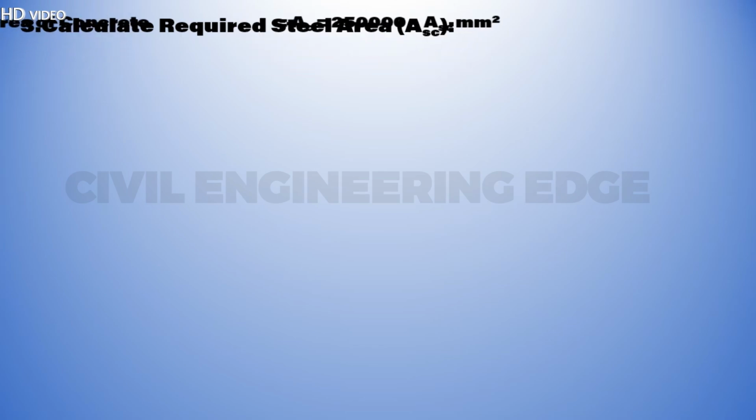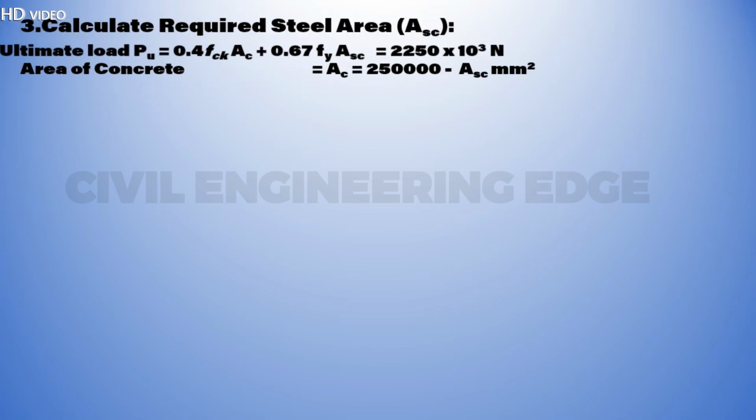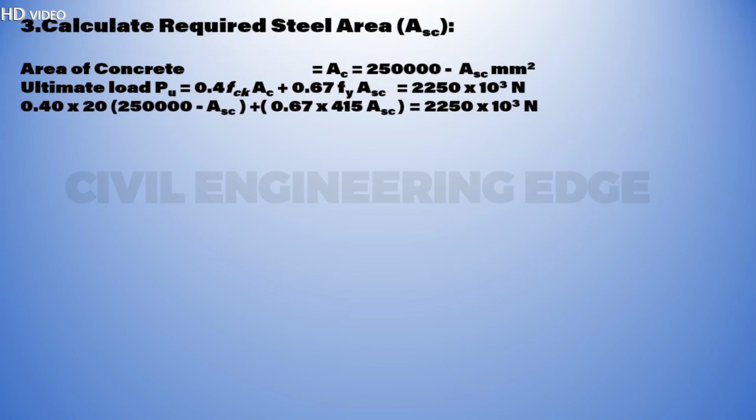For lateral ties design, the diameter of the lateral ties shall be not less than 1/4 diameter of the longitudinal bars equals 20 divided by 4 is equal to 5 millimeter. Provide 6 millimeter diameter ties. Pitch of lateral ties. The pitch of lateral ties shall not exceed the following.